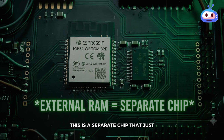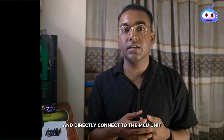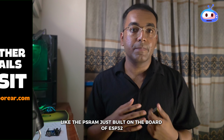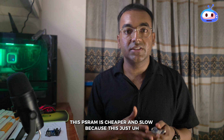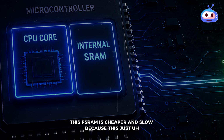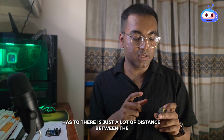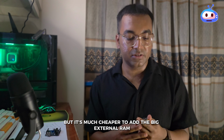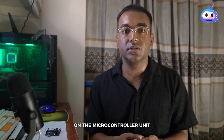This is a separate chip that just connects to the board and directly connects to the MCU using wires, also known as traces. So external RAM like the PSRAM is just built on the board of the ESP32. This PSRAM is cheaper and slower because there's a lot of distance between the CPU and the RAM, but it's much cheaper to add a big external RAM onto the board than to use the RAM on the microcontroller unit, or the MCU.